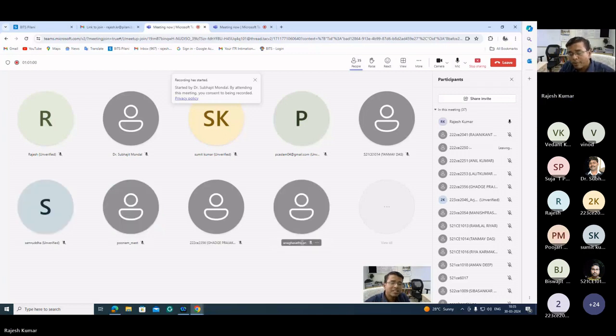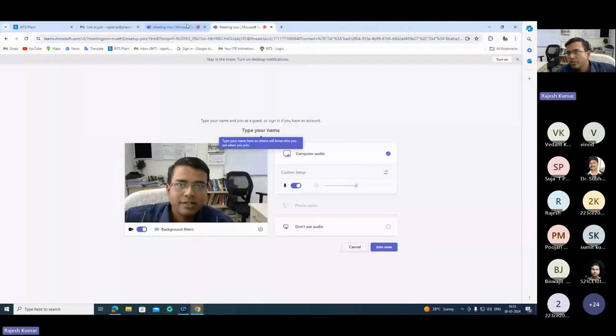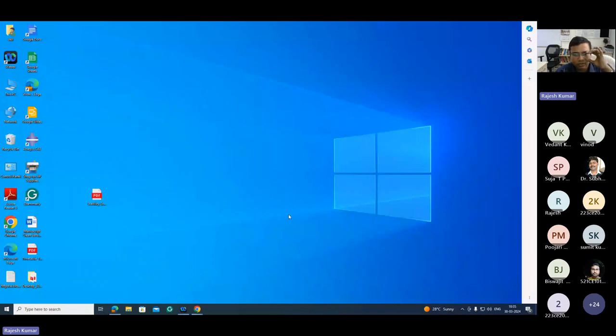Okay, so first you have to find the load while designing, how much load is coming to the structure, and then due to that load, you have to find the stresses. Then we check the stability. You give a small perturbation and see whether it comes back to the original configuration or not. If it comes back, it's okay. If not, then you have to take care of that. You give some stiffness, increase the thickness, such that the member is able to take that amount of load. So you can avoid it using these concepts. Okay, next slides I'm going to discuss. Now I hope it is clear what stability is.